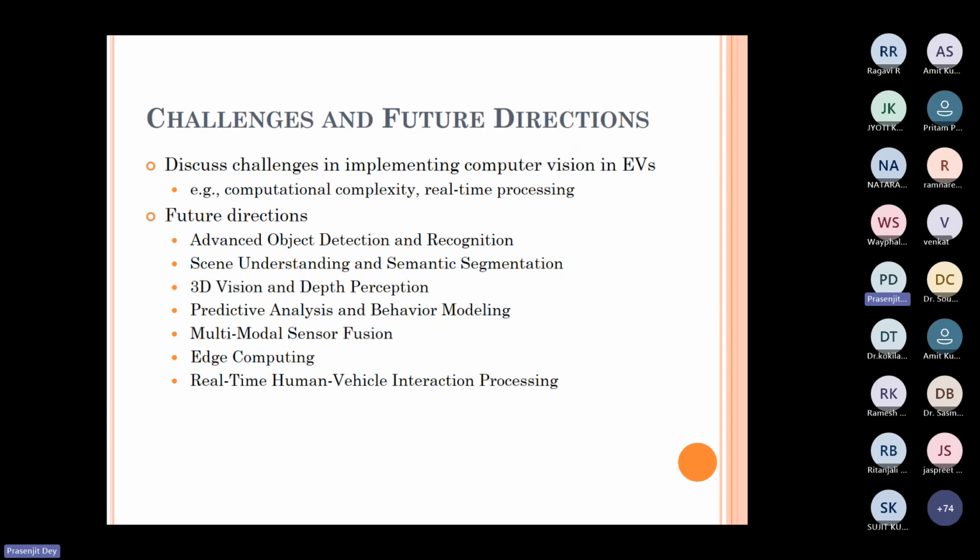Whereas if we provide minimum computational facility to the vehicle, in that case, all the data cannot be processed at runtime, so it will go to the cloud server, and there may be a network issue, because it will take a lot of time to send all those data to the cloud computer. Then the cloud computer again makes a decision and passes it back to the vehicle computer. So the network latency comes into the picture if you use cloud computing.